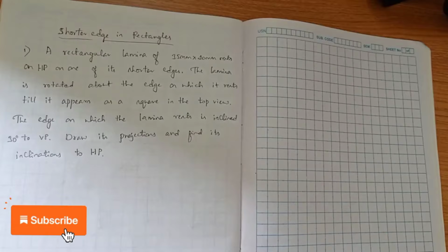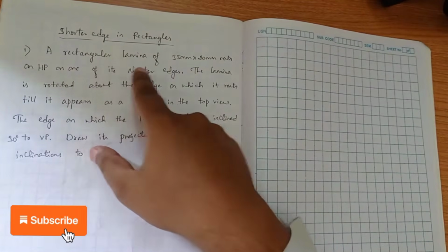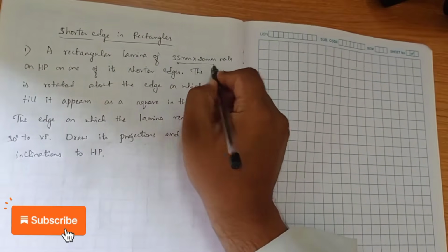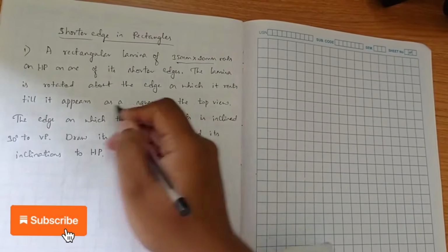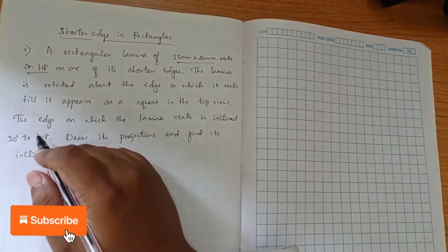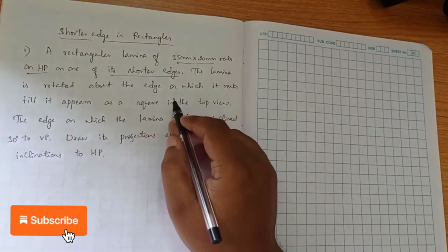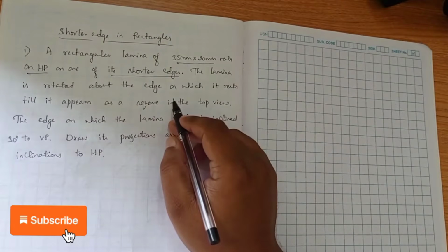Today we are going to learn the shorter edge problem in rectangles. So we have to see the question first. You can see a rectangular lamina of dimension 35 into 20 mm. This rests on HP, so in the first position it is resting on HP on one of its shorter edges. So we have to construct a rectangle with the shorter edge here.